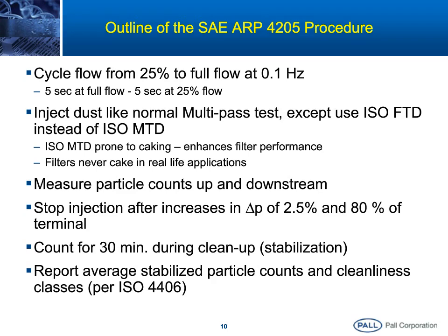This test uses a finer grade of the silica test dust called ISO A2 fine test dust, compared to the multi-pass test and the DFE test that use a coarser grade, which is ISO A3 medium test dust. Experts agree that the coarser test dust is more prone to form a cake under certain conditions on the filter during the test. This caking of the test dust tends to artificially enhance the performance as the cake itself acts as a filter.